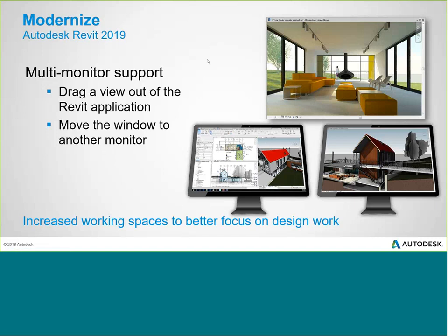So the example we have here in this slide is if you have your plan views on the left and you wanted to see a presentation or rendering on the right, you could always maximize that view. You can do this with any of the views. So you could have a schedule open on one screen, you can have the floor plan view open on another, and it just allows for a much cleaner workflow when you're working in the program. You don't have to extend your desktop or anything like that.